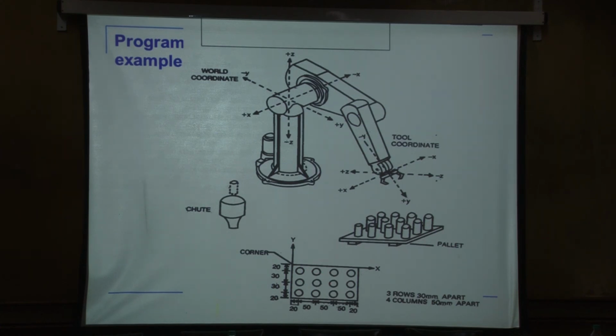So we are teaching one point. Which point we are teaching? The corner point. So the corner point is this one. Okay. So I want to catch an object. To catch an object, you have to go to the CG and the top of the object. So I'm shifting the corner by 20. So this is 20. That is 20 dimension. So it is plus 20, minus 20, 60 is height in terms of from here till there is 60.